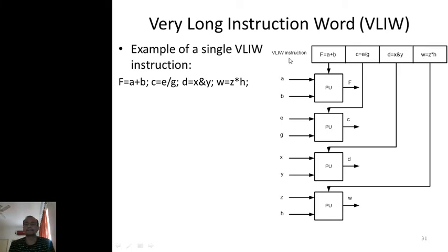So when this instruction gets decoded, the processor knows that this is a VLIW instruction, so it feeds all this data to all these parallel units, right? All these units have the arithmetic logic capability to perform addition, division, multiplication and logic operations in parallel and provide simultaneous outputs. And at the W stage, the result stage, all these results are written into their respective registers or memory locations in parallel. So this is, you can say, one instruction level parallelism.